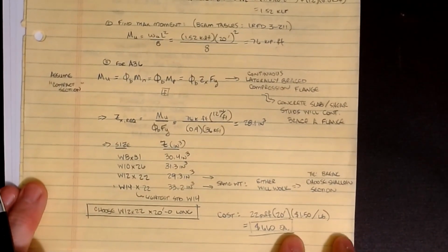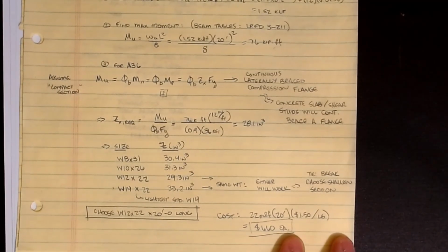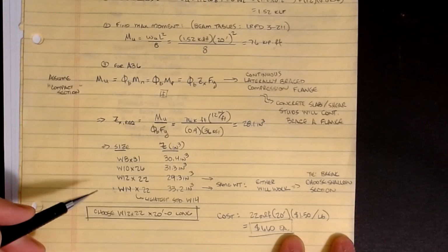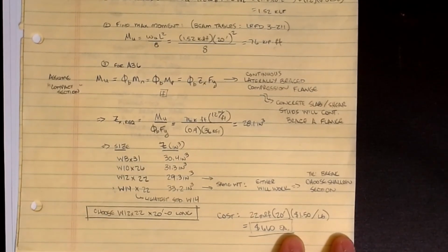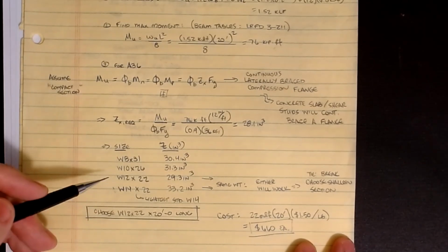And so we'll get into some calculations that we'll do eventually called serviceability calculations, where we're measuring deflections. Deflections are functions of the moment of inertia, and the deeper the section, the higher the moment of inertia. Often, if I can get away with it, I'll take the larger one because it will help control my deflections a little bit better. But there's lots of ways to break the ties. For us, we don't really care.